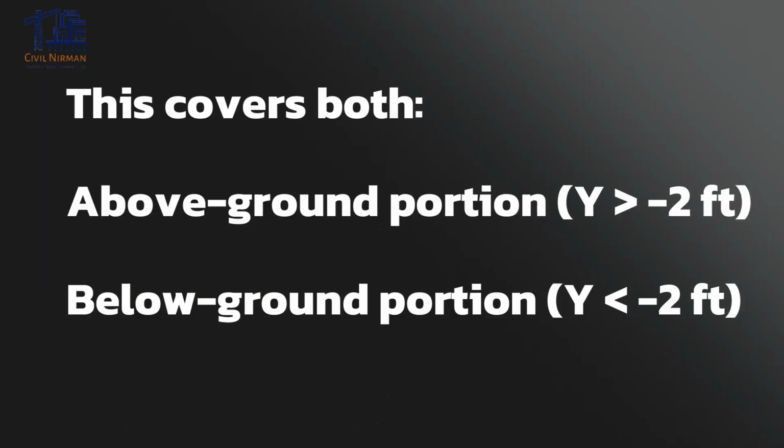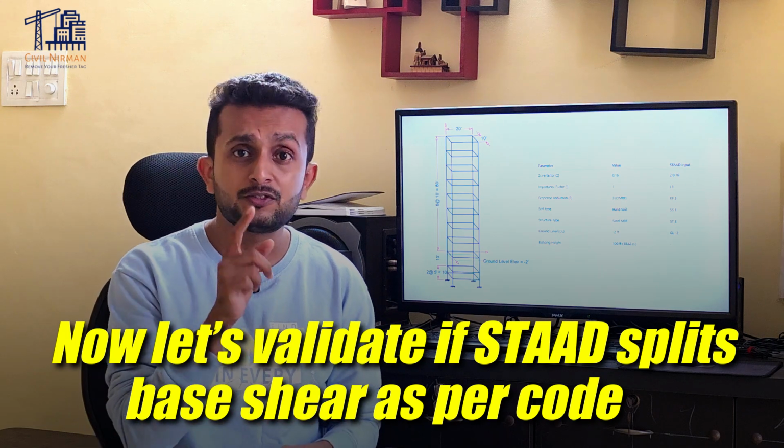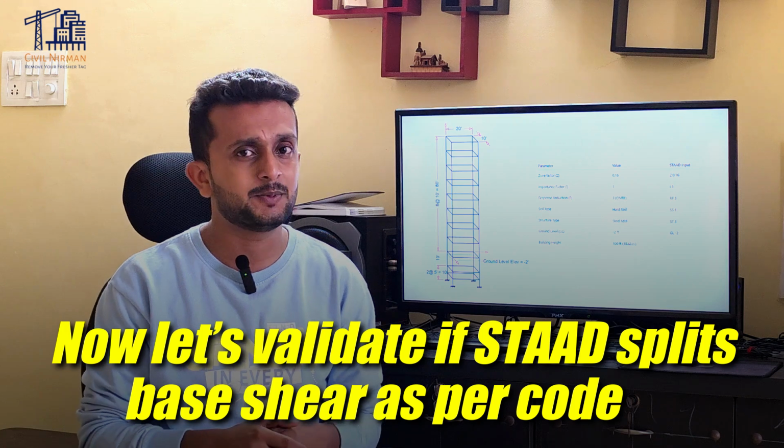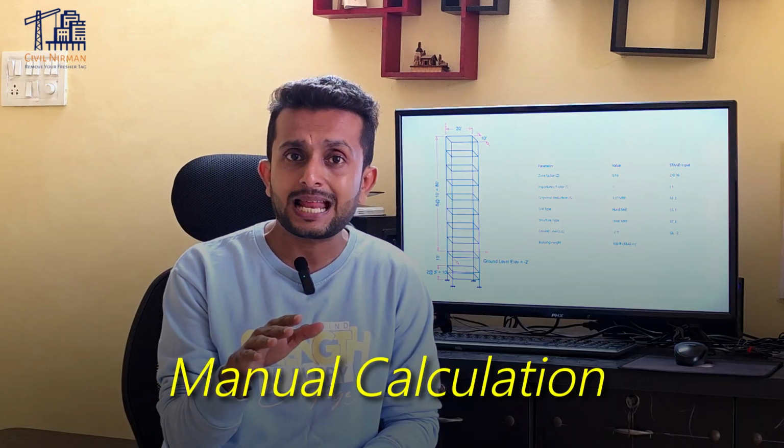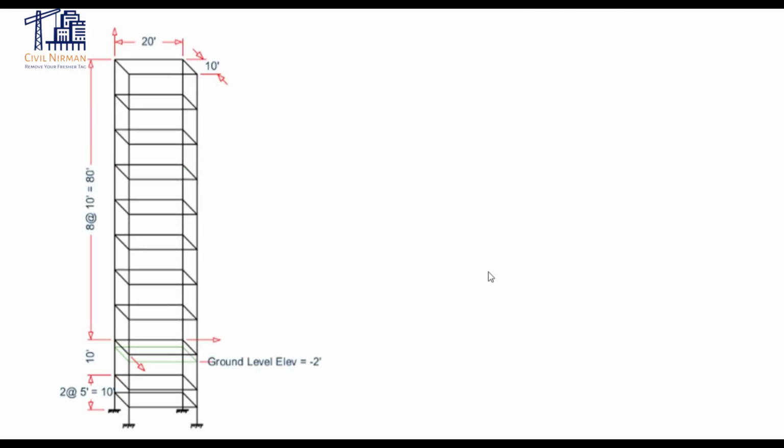Now see, this covers both the above ground portion, that is minus 2 feet and above, and the below ground portion, which is below minus 2 feet. Now let's validate if STAAD splits the base shear as per code. Also, I am going to show you the whole manual calculation which I have covered in this session. So let's understand how we can go for the manual calculation check.